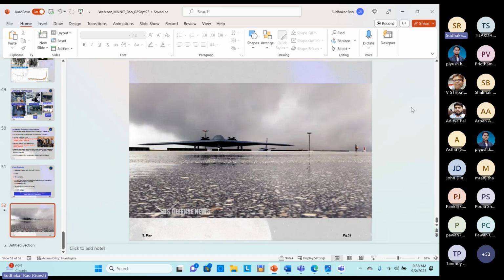Scan loss depends on the element size, because scan loss comes mainly from the element roll-off. So that you can estimate very easily. The phased array design looks complicated, but you can design a phased array in probably a couple of hours. People tend to, in academia, I see a lot of papers, even for 30-degree scan, use half a lambda wavelength. When you use that, the number of elements becomes very large, thousands or so, maybe more than that.